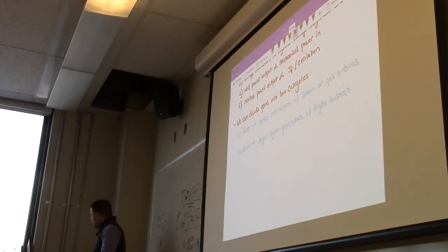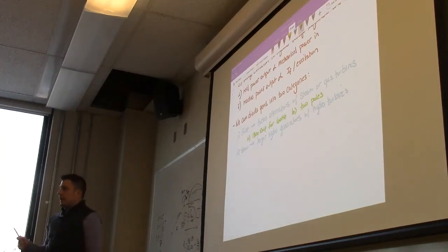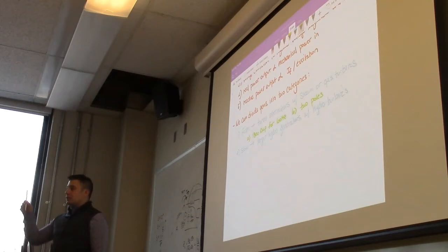And so we can also give these some other attributes. So this will operate at 1800 RPMs approximately for 60 hertz generation. And it will have 2 poles, meaning that the rotor will only have 1 north pole, 1 south pole, okay? As opposed to, you can have implementations where there's multiple poles that kind of go around like that.